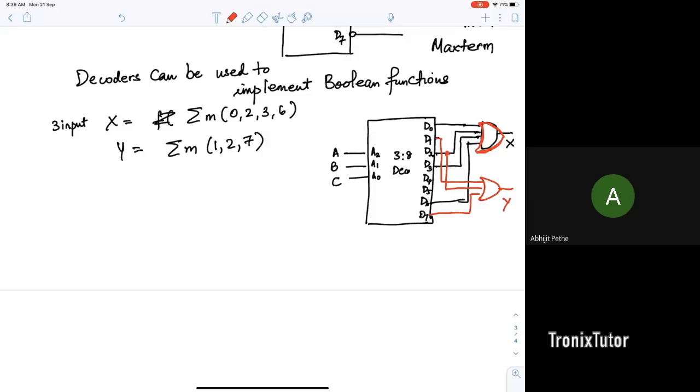So again, you see that this makes life much easier. Designing something off this would be much easier. So what do you think is the drawback of designing using decoders? What can you guys think? Why don't people use this more often, especially when you're at NVIDIA? Exactly, right? It's going to be slow because the decoder is going to implement 3-input AND gates, for example, in this case, and 3-input AND gates are going to be slow.